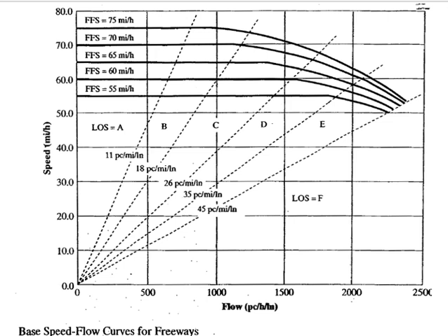Why? Density equals flow rate upon speed. Clear? Do I have flow rate here in the graph? Do I have speed here in the graph? Can I do flow rate upon speed? And if I do flow rate upon speed, it will be the slope of the graph. So this is how we plotted the lines. We use the density and we said, okay, this is my tangent theta, flow rate upon speed, and we draw the line according to that.